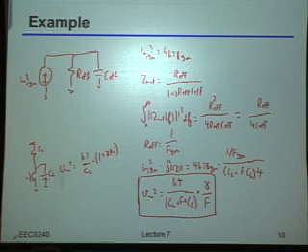Okay, so notice that here with this feedback amplifier, what's actually happening is, of course, the load capacitance, instead of just being a regular load cap, now we have that feedback part that's adding on some extra capacitance as well. Okay, so that makes sense, although that's probably not too big of a deal, right? Presumably I can size those capacitors so that they don't have too big of an effect.